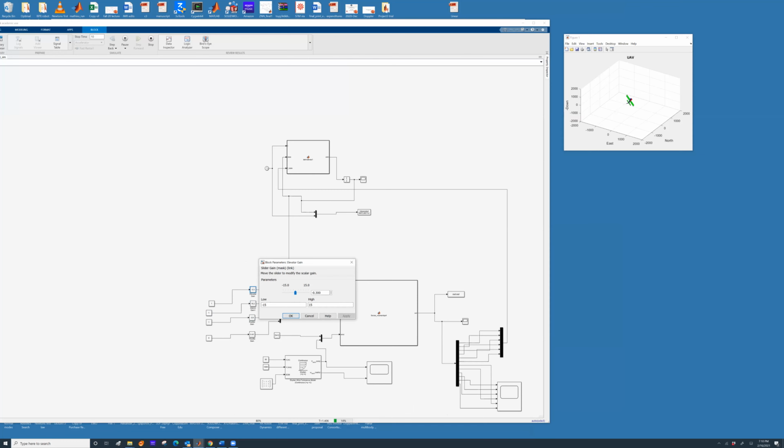If you want to change the elevator gain, you would change the elevator gain. And now you can see clearly the aircraft has become unstable. So what you can do to start is make it 0. Please note, this simulation is incorrect because these values are in degrees, but your values need to be in radians. And this simulation is shown if you change your throttle gain to 0.1, which means you will notice gradually the plane sort of becomes stable.